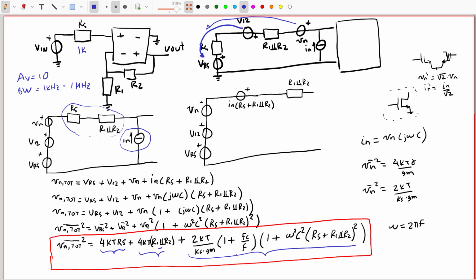Let's take first the resistors, R1 and R2. If we make these two resistors very small, the current that I will need to handle signal swing at the output will increase. The output will typically be connected to a load, and it is also connected to the feedback. And then I will need some current to be able to produce a signal swing at the output.